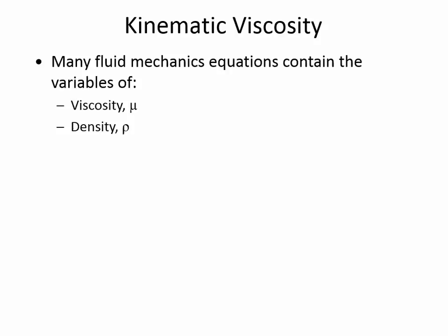There's a lot of different words associated with viscosity. Sometimes we just call it viscosity. There's also absolute viscosity. There is kinematic viscosity. And so let me tell you what kinematic viscosity is. A lot of the equations that you'll be working this semester and beyond have both the viscosity and the fluid density in the equation. And so kinematic viscosity is an effort to kind of normalize fluids' viscosity relative to their density.